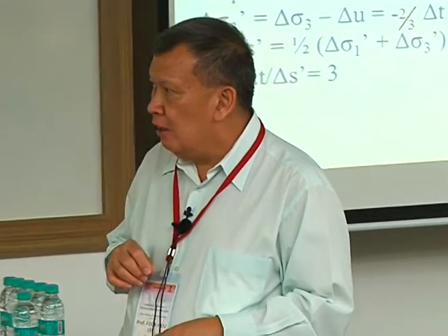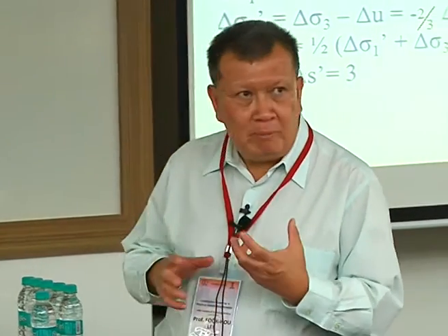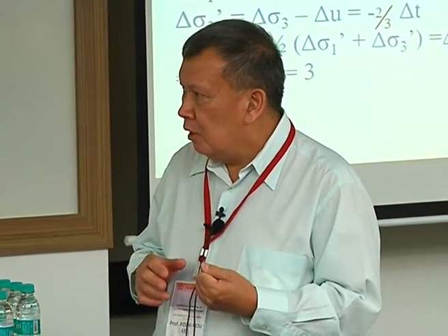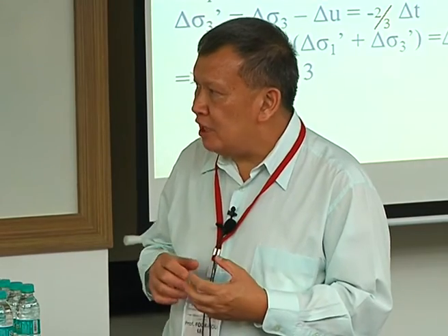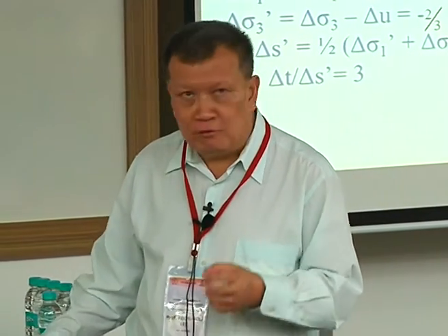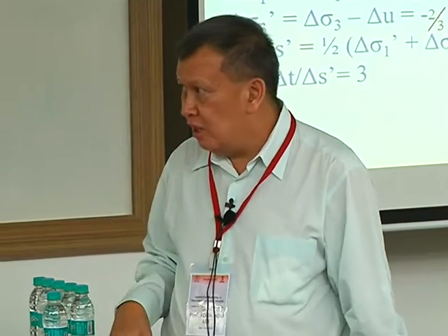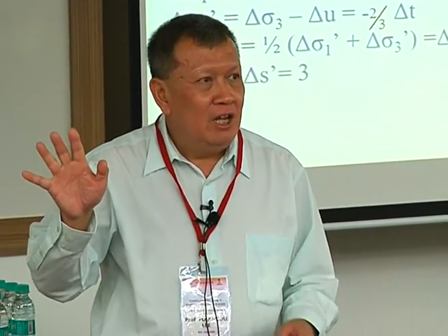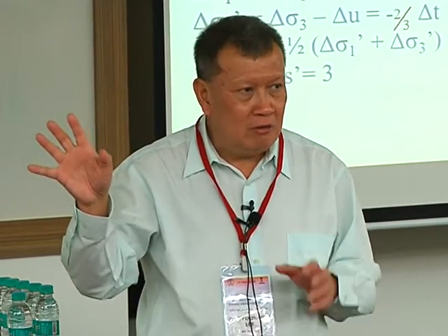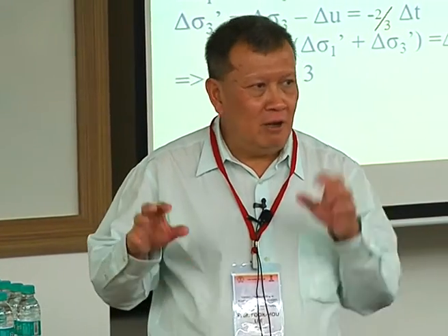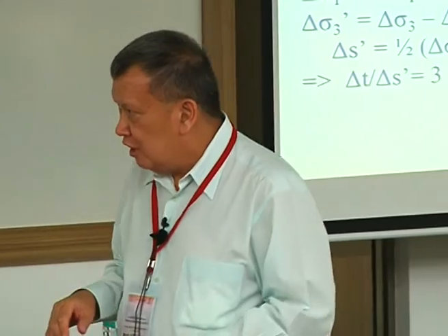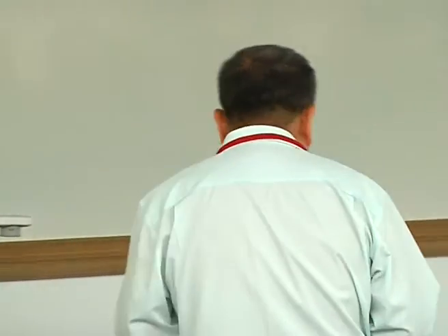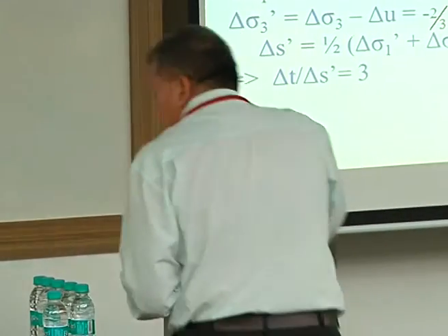Skempton basically tries to describe excess pore pressure generation in terms of changes in the total stress. He doesn't want to describe it in terms of effective stress, because you only know the changes in the total stress. You don't know the changes in the effective stress. You want the excess pore pressure generation. And the Skempton's pore pressure equation, can I use the board?